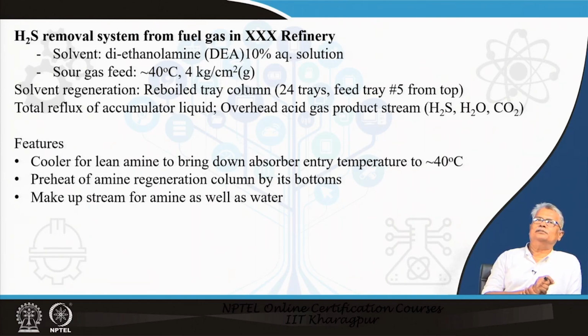You will also see, if you are really following this, that there will be a cooler using cooling water for the rich amine to be brought down to the absorber entry temperature of around 40 degrees centigrade. Typically, it is around 45. There will be preheat of the amine regeneration column feed by its bottom, that reduces the heat input to your column. You have to have a makeup for the amine as well as water.